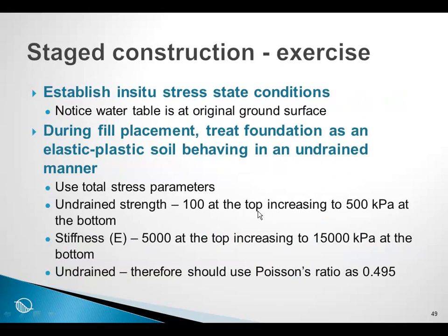So here is the exercise for stage construction. We're going to start by establishing the in situ stress conditions. Notice that we have a water table at the original ground surface. As a result, we will have to use effective drained parameters in order to get the total stresses correct. And then we're going to switch to total stress parameters for the loading phase. During the fill placement, we will treat the foundation as an elastic plastic soil behaving in an undrained manner. We will use total stress parameters.